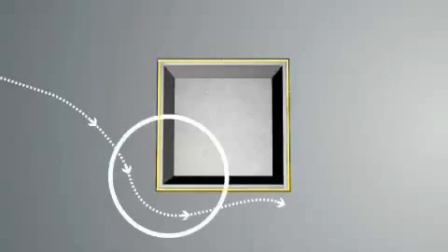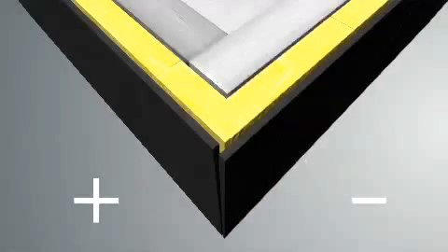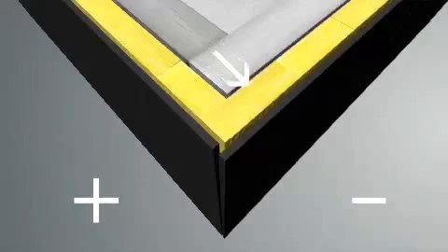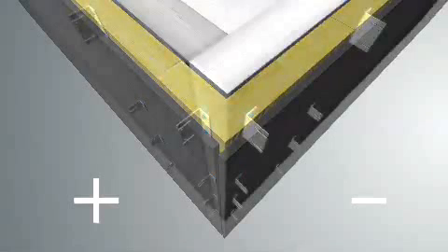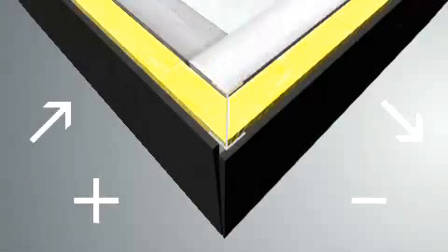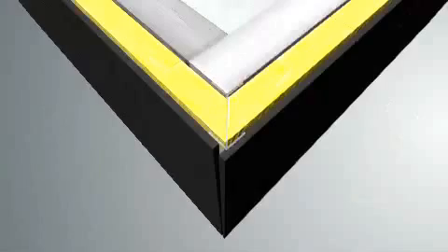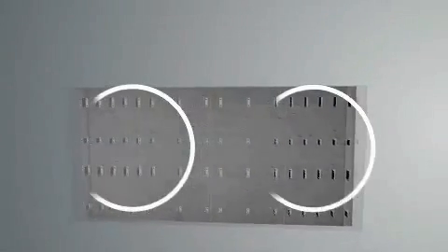External corners are one of the most vulnerable areas to wind. As well as the wind pulling the panel from the outside, the back of the panel can be also subjected to pushing from the cavity. To counteract this, a continuous vertical cavity closer is introduced so that the wind pressures are separated. Another solution is to fix extra supports on both sides of the corners of the facade.